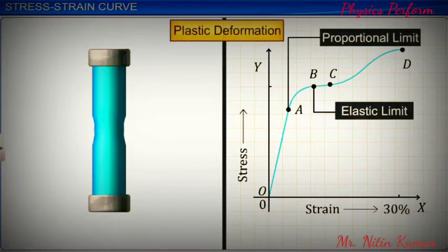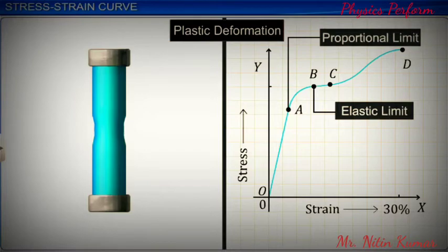The amount of residual strain that remains on removing the load can be determined from the stress-strain curve. For example, if the load is reduced to 0 from point C, the residual strain can be found by drawing a line parallel to OA at C. The point where this line intersects the strain axis gives the residual strain or permanent set. The stress now increases with strain, but less rapidly.